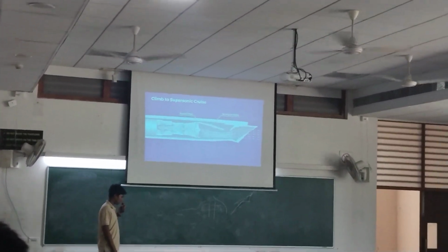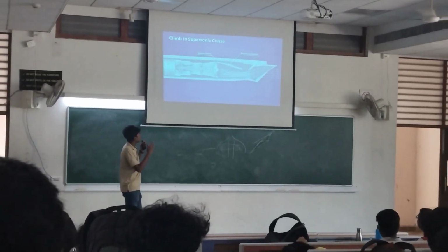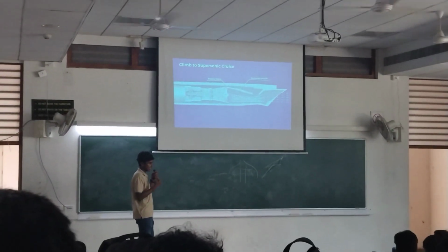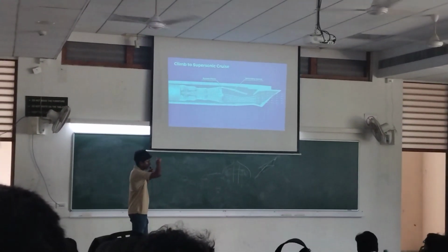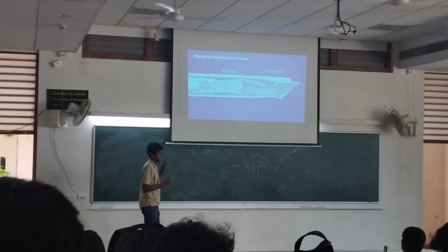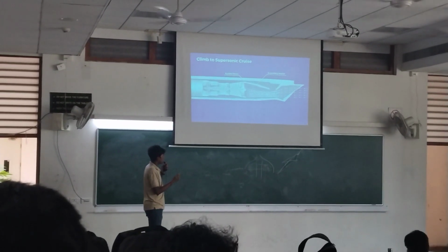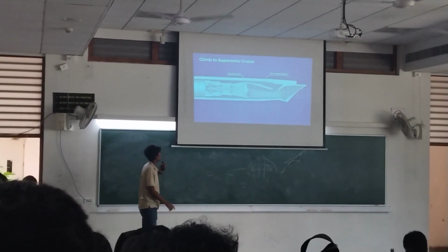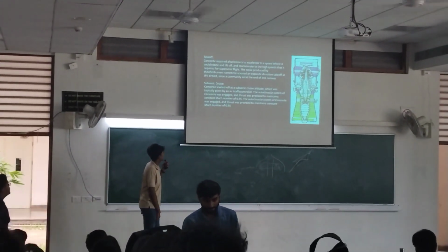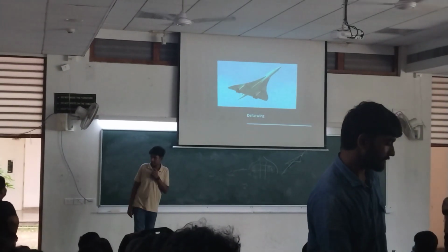So for supersonic speeds, we don't need a lot of air. So the ramp doors open up, so that the air is converging, and we saw in the previous graph that when the air converges, the speed decreases. So the speeds decrease to ease the combustion, and the bypass doors are open for cooling. These just explain what I said.